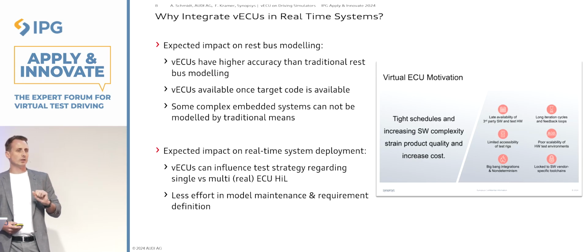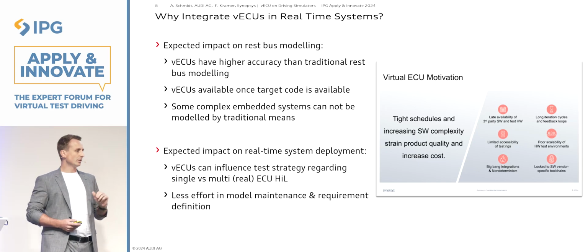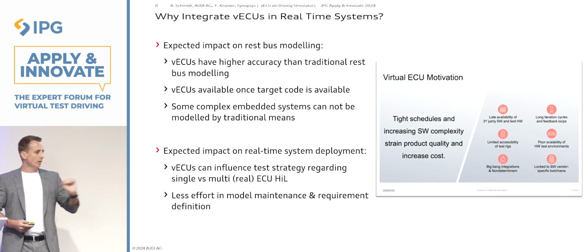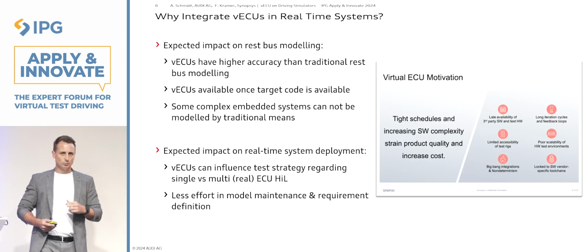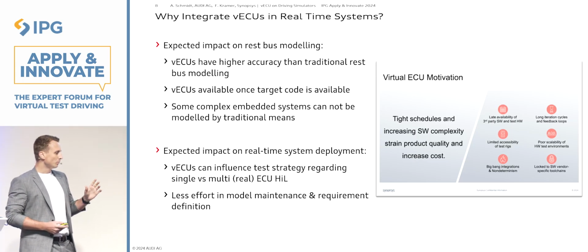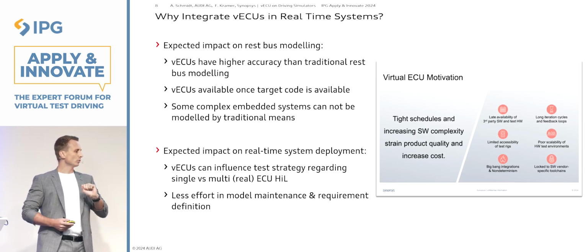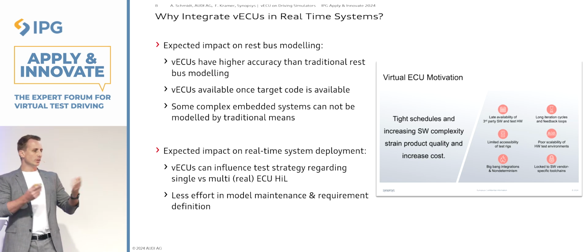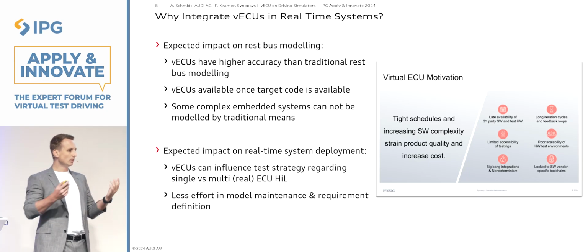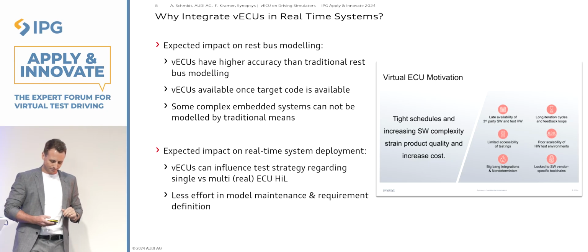But if you could reuse a very validated virtual equivalent of a real-time system, you could say, okay, I have a system under test. This will never go away on a hardware-in-the-loop setup, right? Because that's why we do hardware-in-the-loop testing. But if you could say, okay, I could add maybe 1 or 2 virtual ECUs next to another real one, I could achieve a much cheaper system simulation instead of integrating a HIL which contains 5 real systems. So that's the second area where we expect an impact.